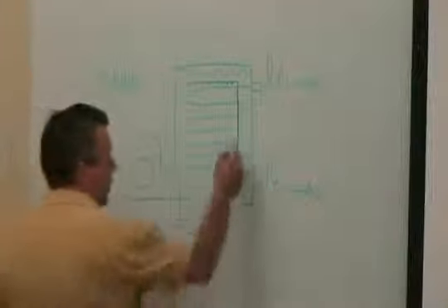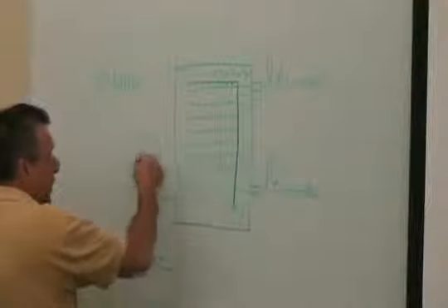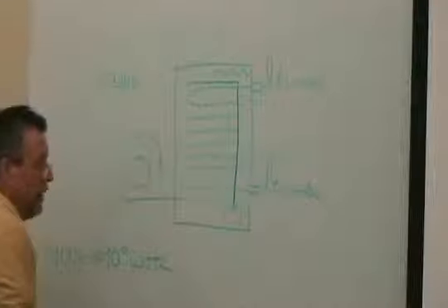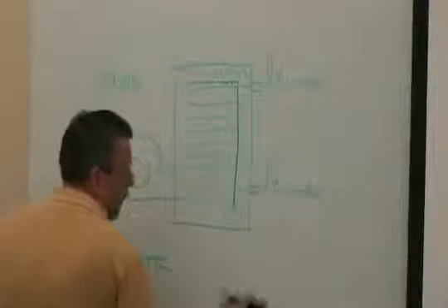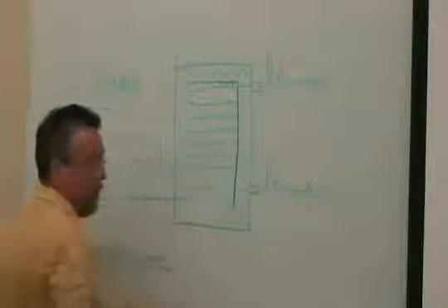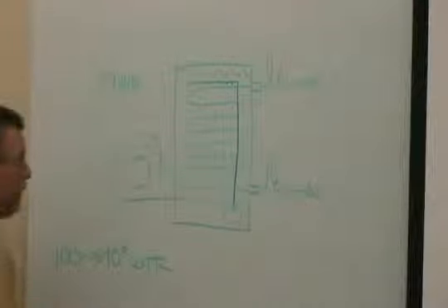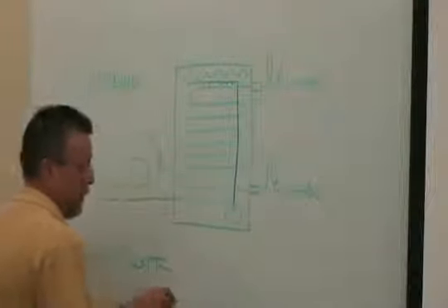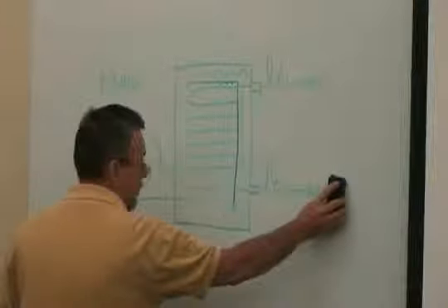First stage might be the spray pump over the heat exchanger, running water through there. Second stage might be bringing the fan on. And like I said, I can produce about 90-degree water with 100-degree return coming back in. And again, that's at the extreme condition where everything's heated. Again, the heat pump loop is going to operate in that range from 60 to 100 degrees.